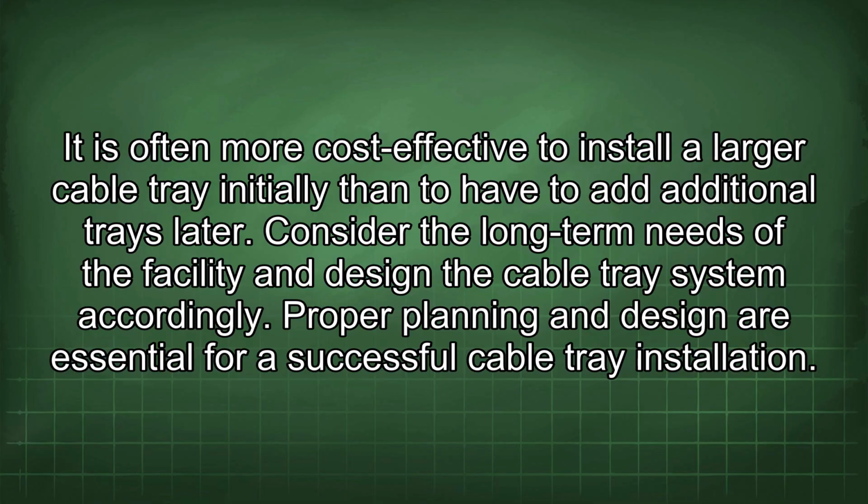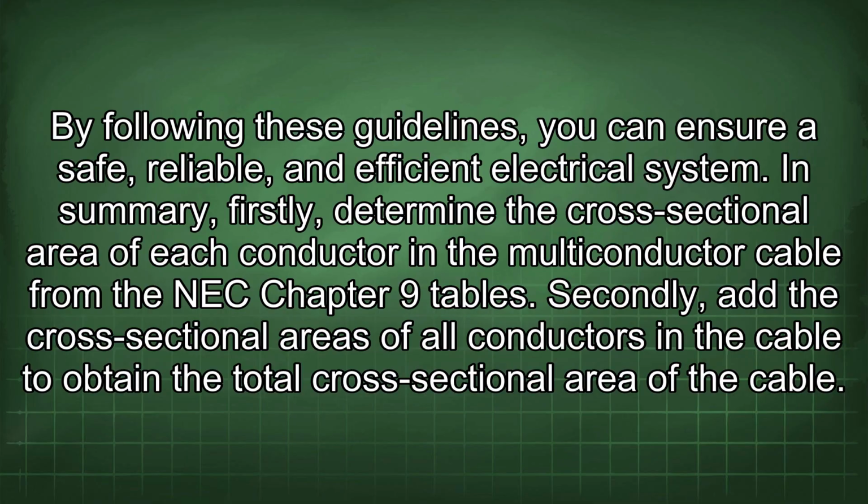Proper planning and design are essential for a successful cable tray installation. By following these guidelines, you can ensure a safe, reliable, and efficient electrical system. In summary, firstly, determine the cross-sectional area of each conductor in the multiconductor cable from the NEC Chapter 9 tables.